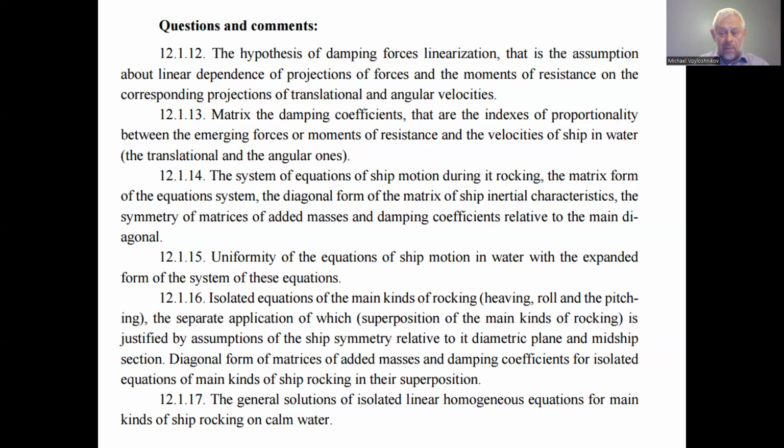So we have the matrix, and the motion in each direction causes a force arising in the same direction and in all other directions. And that is why we have the matrices of the added mass factors and the matrices of the damping coefficients, which look very similar, but usually we denote the added mass by the letter mu, and the damping coefficient by the letter lambda.